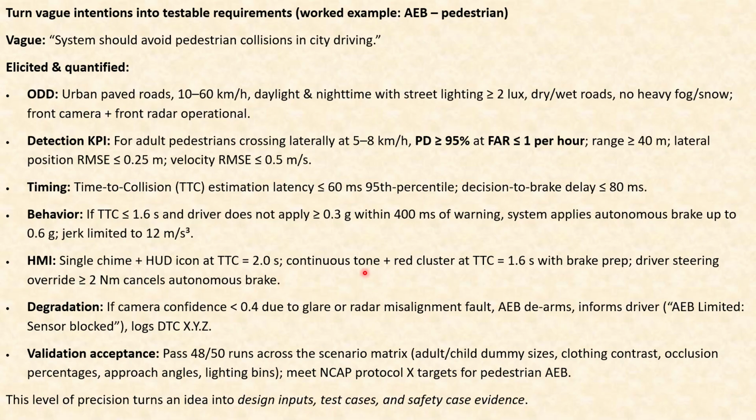So this continuous tone and red display should happen if time to collision is 1.6 seconds with brake preparation, and driver steering override greater than 2 Newton meters cancels the autonomous brake. If the driver is alert and applies greater than 2 Newton meters, it cancels the autonomous brake.